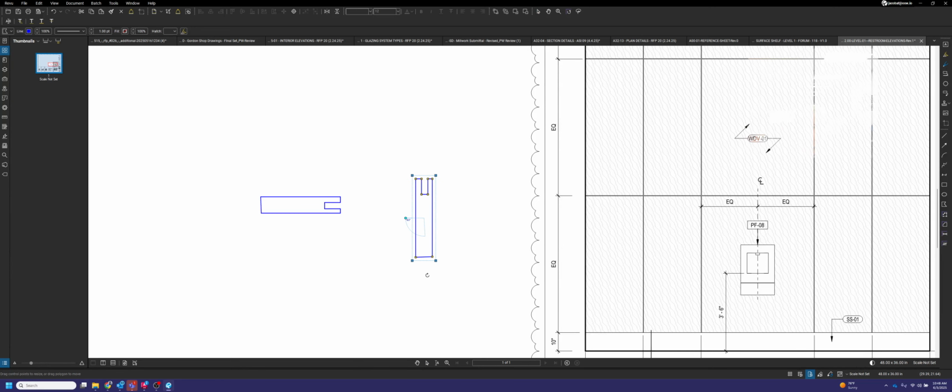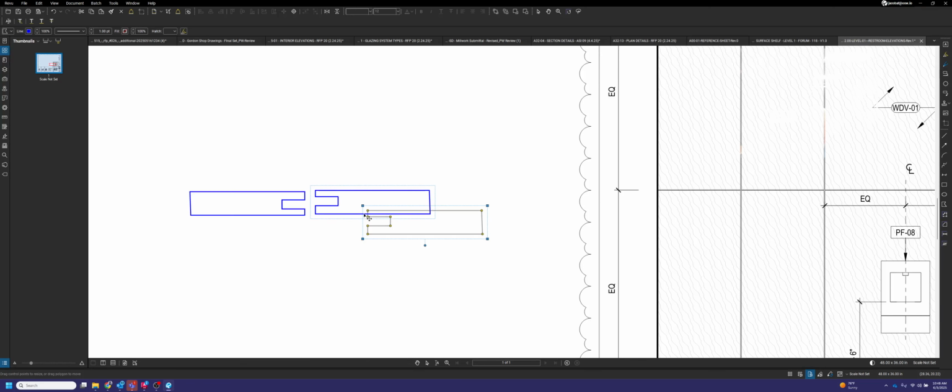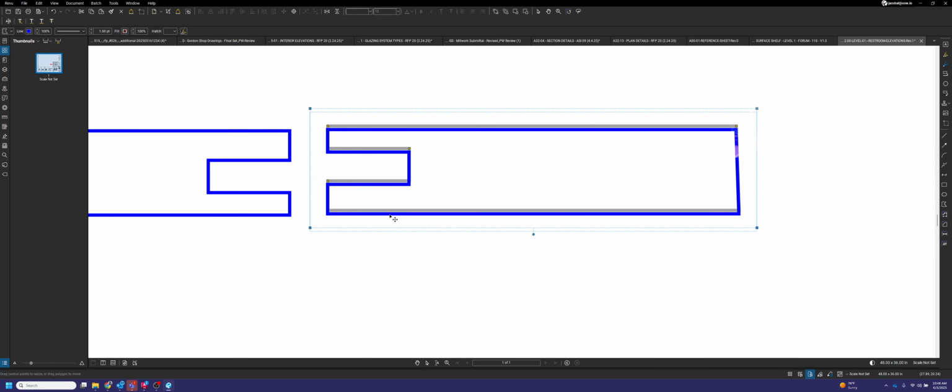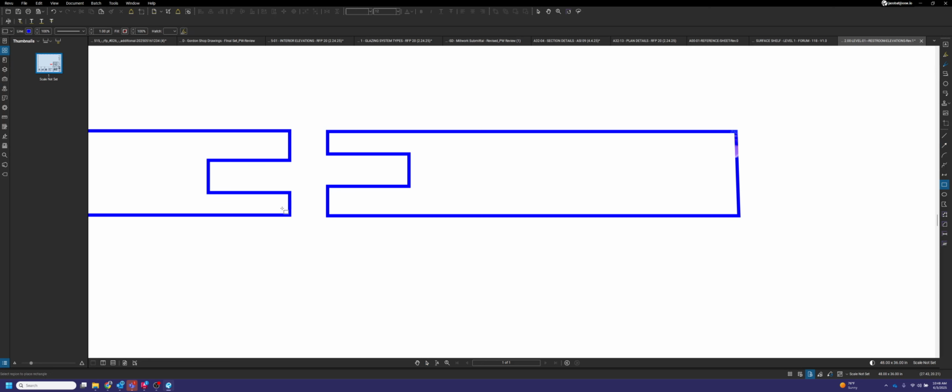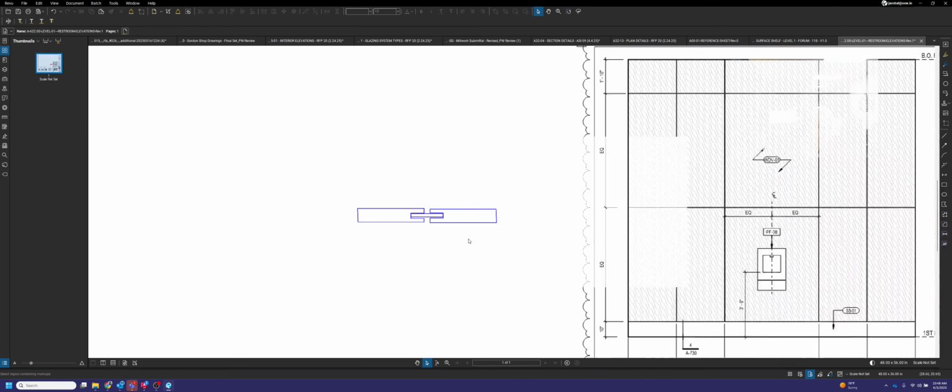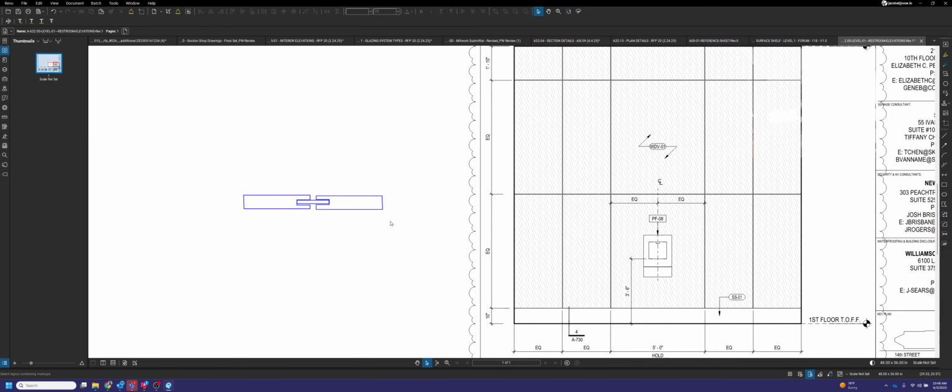They are going to look similar to this. There'll be a flat piece of material right in the middle, just like this. And, well, these are a little bit wonky, but you'll get the picture though. So that's what a spline joint would look like, and these will be 1/4 inch wide in between these panels here. That is on-site standard, typically, unless noted otherwise by an architect or a project manager, that in between panels we usually will put a 1/4 inch line reveal there.